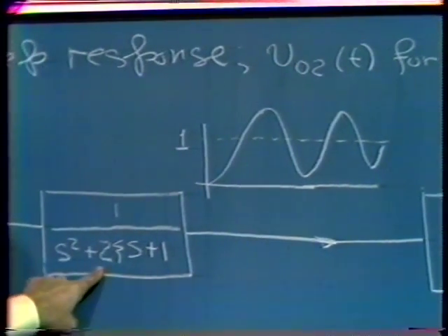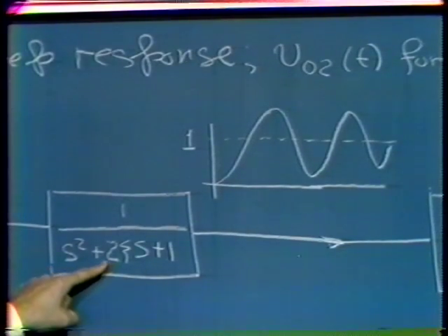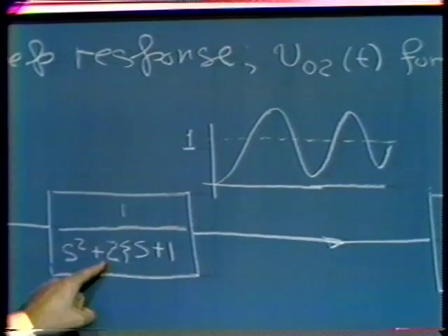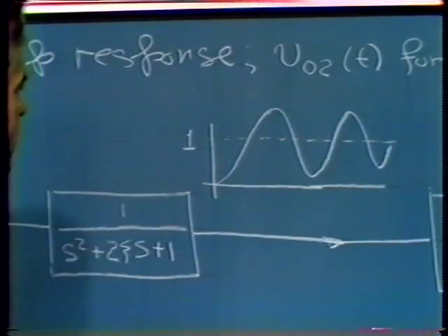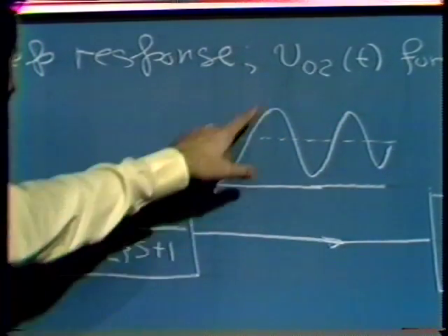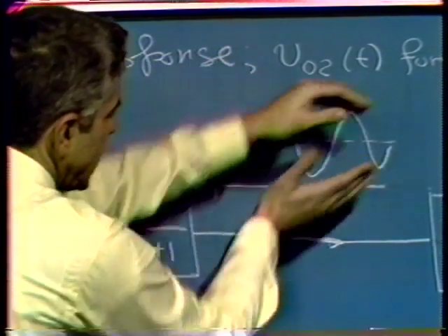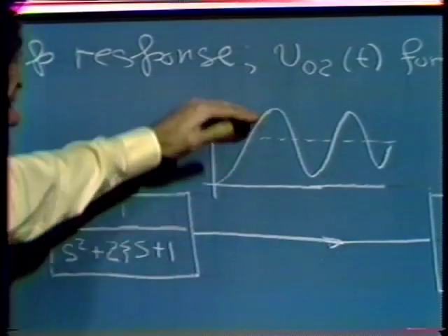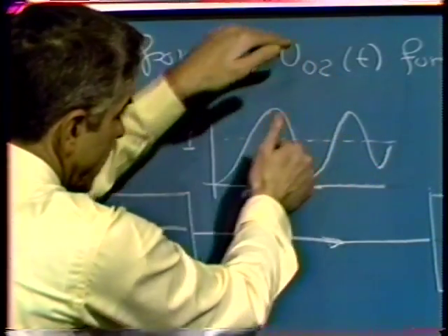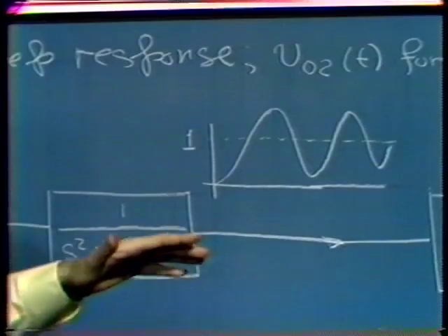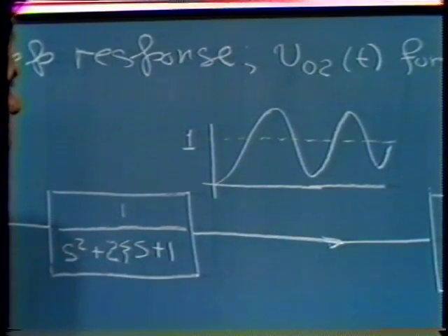We've looked at the step response of a lightly damped complex conjugate pole pair several times before. It has this general form. That was a response we looked at several times ago. And as the damping ratio gets smaller and smaller, the rate of decay of this waveform gets progressively slower. We have more and more cycles of oscillation before it dies down to a given amplitude.